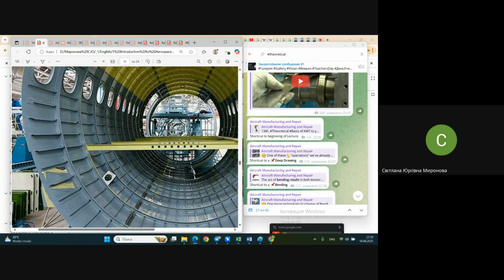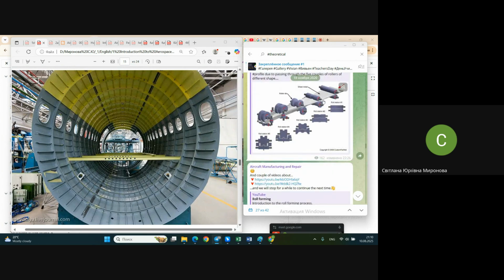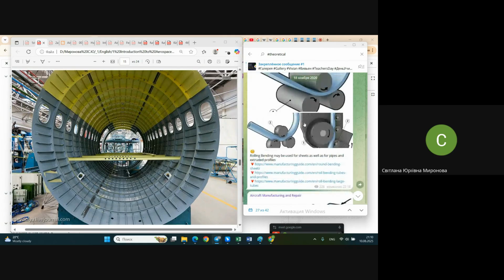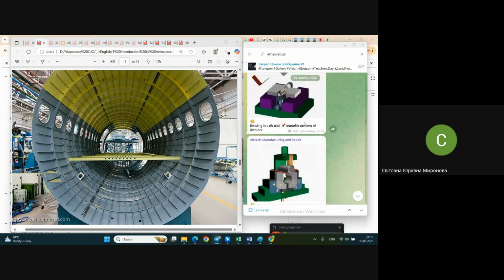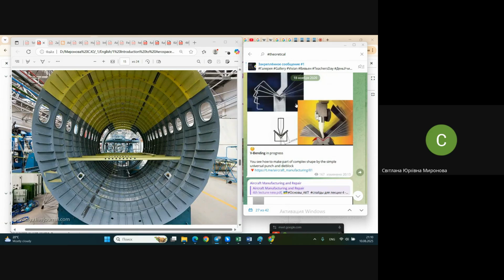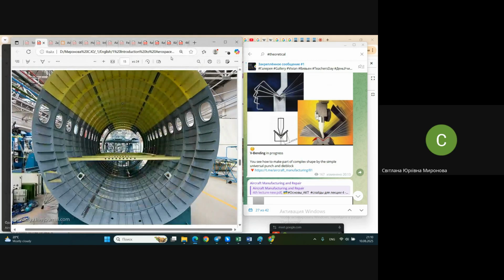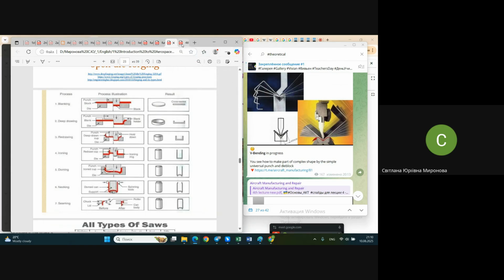If they are made of sheet, because it is a more delicate structure, in this case we may use either sheet rolling, or the bending machine to create stringers like this. And finally it will create some shape that we need actually. Typically it's a Z shape, maybe an L shape, typically Z shape for stringers when it comes to aircraft manufacturing.